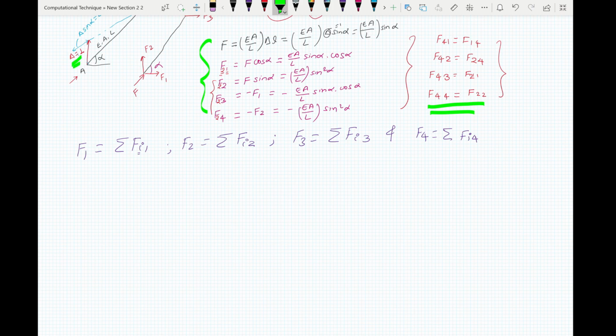Unit displacement means these are all the stiffnesses in each direction, because by definition stiffness K equals force by displacement. When displacement equals 1, it will be equal to force. This is the force required to have unit displacement in the direction of the force applied. So these are all your stiffness values in the corresponding direction.